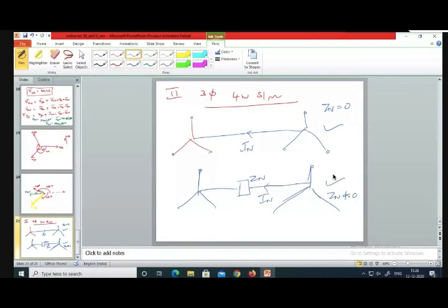Clear? So when there is current flowing, how to find the current? In is equal to IR plus IY plus IB. So this is the neutral current. The neutral current is made up of all the currents in the phases. The neutral wire will always have negligible impedance, that is, it is assumed to be 0. But in some cases, the neutral impedance is significant.